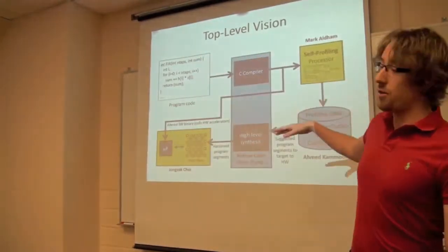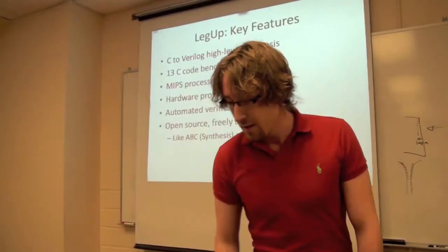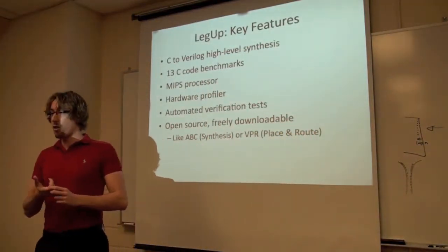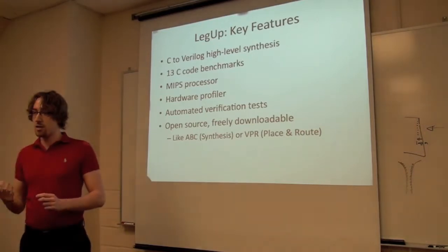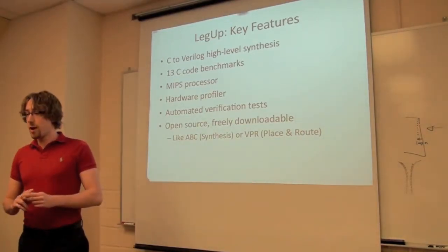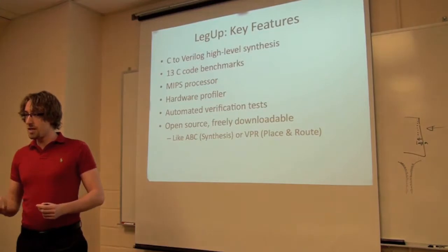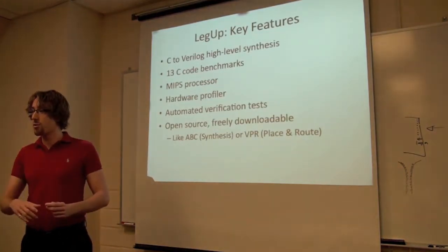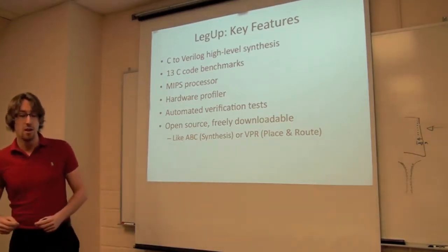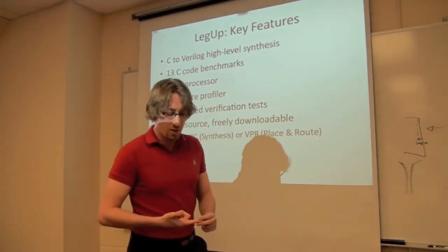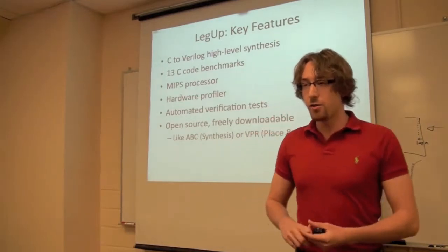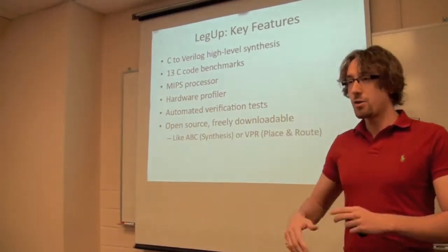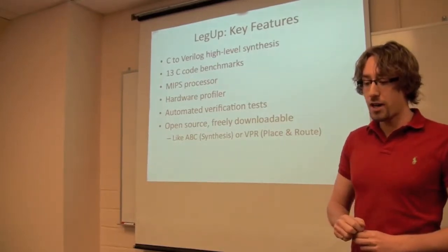These are the people involved in the different parts of this project. The key features we're offering with LegUp are a high-level synthesis framework that can take in C and produce synthesizable Verilog. We're also going to provide some C benchmarks, which are typical of the kind of code you'd want to move into hardware where you could see some advantage. We have a MIPS soft core from the University of Cambridge, called Tiger MIPS, and we also have a hardware profiler, which will let you determine how your program is running.